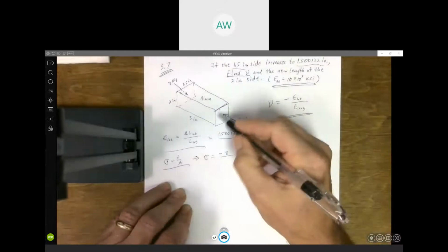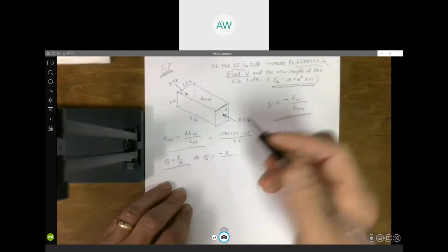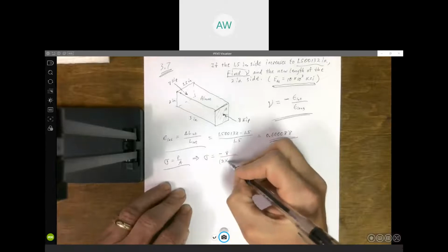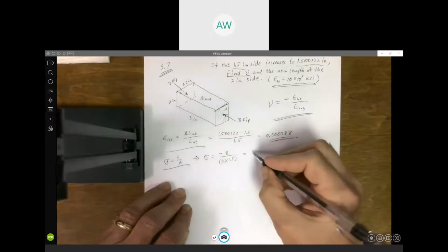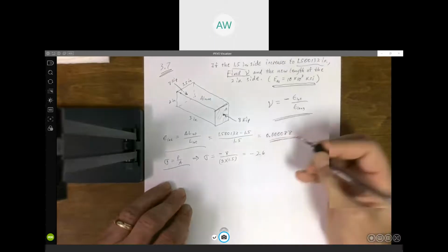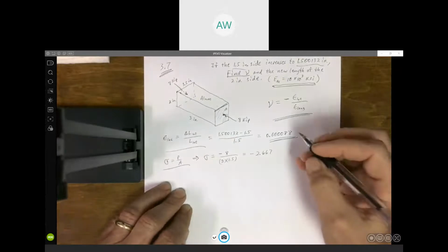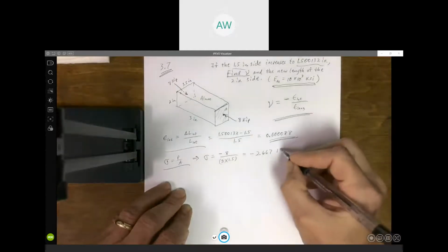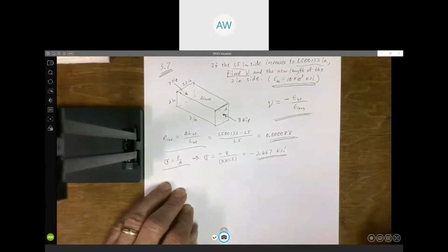Now the cross-sectional area here, it's just the area of a rectangle. It's 2 inches tall, 1.5 inches wide. So 8/3, 2.666. I don't know how, 2.67 probably be sufficient enough. But that's what the normal stress is in this aluminum bar.